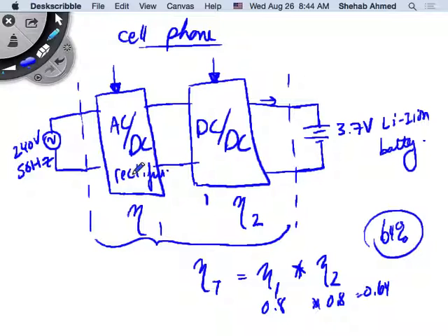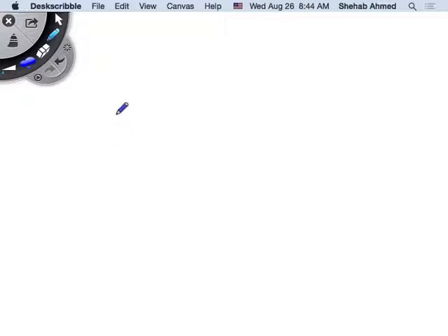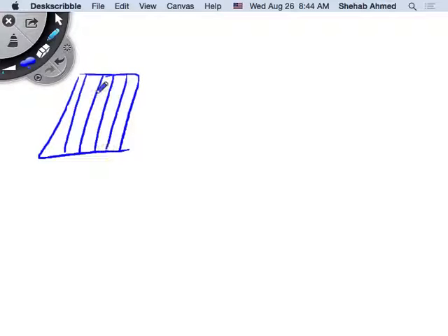Is this more complex topology going to have a better efficiency or not? You will have to study that, right? Probably yes. From a system efficiency perspective, single stage power conversion topologies are more favorable, and that's a lot of the research that's going on. For example, let me give you an example of where that is actually happening considerably. So you have a PV panel. Right? This PV panel is giving what sort of output? AC, DC?